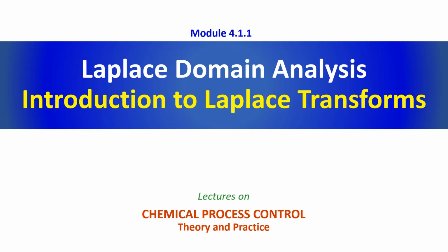We are doing this because no matter what technique you use, whether you do empirical modeling or first principles modeling, ultimately one ends up with, after linearization and things like that, the most basic dynamic elements: linear time invariant ordinary differential equations, and these differential equations can get larger and larger in terms of their order. We've looked at first order, second order, but you could have 10th order, you know.